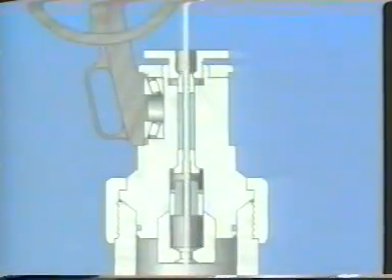In order to accomplish wire line operations, we must attach to the wire line a tool string suitable to the well conditions and the work that is to be performed. The standard wire line work string is used to accomplish many functions. The weight of the tools allows them to fall into the well bore with the force of gravity. The mass must be sufficient to overcome the friction of the wire line passing through the stuffing box and the force of the well pressure pushing up against the wire line where it passes through the stuffing box.